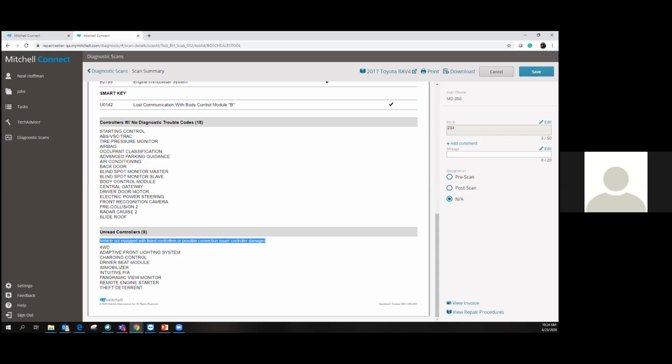Our software is going to read fault codes that were generated by the manufacturer. Now that fault code might be kind of vague, and that's where we can do a little deeper dive. Whether we go into special tests, or maybe data streaming, we can actually read resistance values of the different sensors and airbags in the system. That's where you start using the other options on the tool to do a little deeper dive in there.